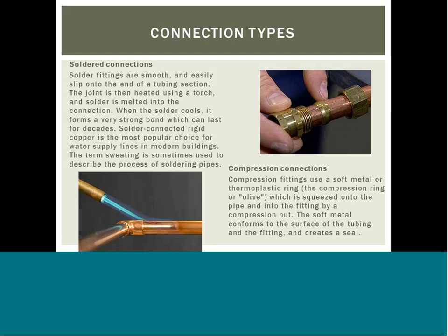Compression connections do not typically have the long life that sweat connections offer, but are advantageous in many cases because they are easy to make using basic tools. A disadvantage in compression connections is that they take longer to make than sweat and sometimes require retightening over time to stop leaks.